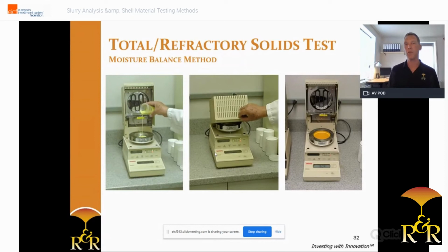It's very helpful because if the results are high, you can have issues with brittle shells, and they will crack at the de-wax. If they're very high, you can also have hot tear defects in your castings or permeability issues like non-fill and gas. When the refractory solids are low, you can have issues with weak shells, and they will crack at the autoclave or at de-waxing and at firing. But also you can have leaks and runouts. But also shell bulging is an important reason for low refractory loadings.